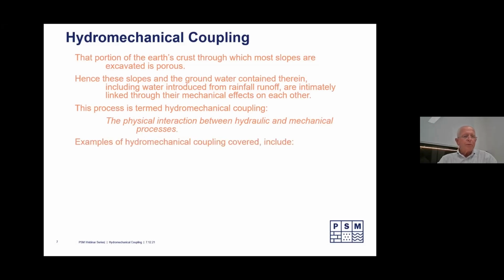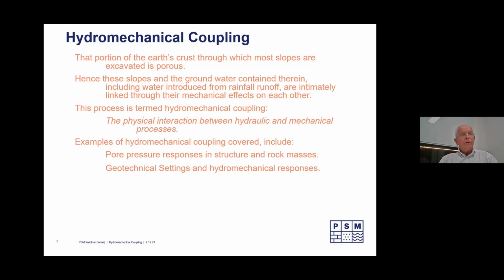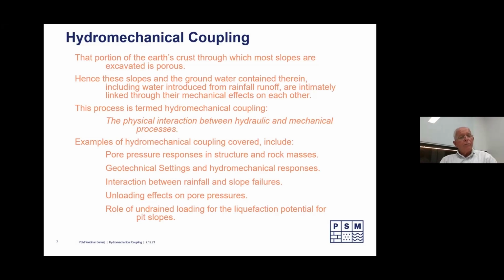There's a number of examples that I'm going to cover in this lecture. Firstly, pore pressure responses, then the geotechnical setting and how that impacts on the process, the interaction with external water sources and how that impacts on slope failures, unloading and pore pressures, and then the role of undrained loading and liquefaction potential, where we get very large post-failure deformations that nearly always have very adverse outcomes.